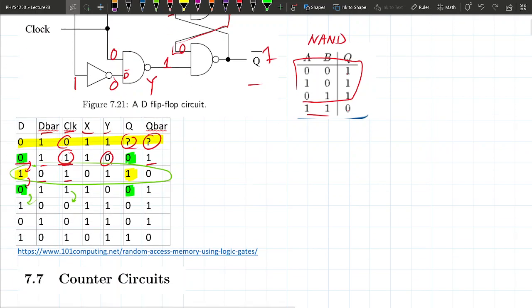So the interesting thing is that, when we did this flip from on green, we changed the D from 0 to 1 and the clock from 1 to 0. The output doesn't change. And this is what the homework is trying to get you to realize when you do this with NOR gates and AND gates.